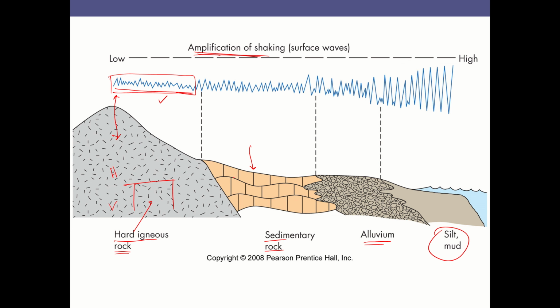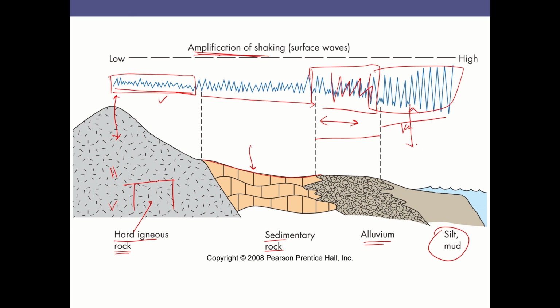Or if the earth surface where we are trying to build is made of sedimentary rock, then there is a slight increase of shaking. And in the case of alluvial soil, there is a larger movement that can be felt, and in the case of other types of soils, muds and so on and so forth, huge amplification can be measured and identified.